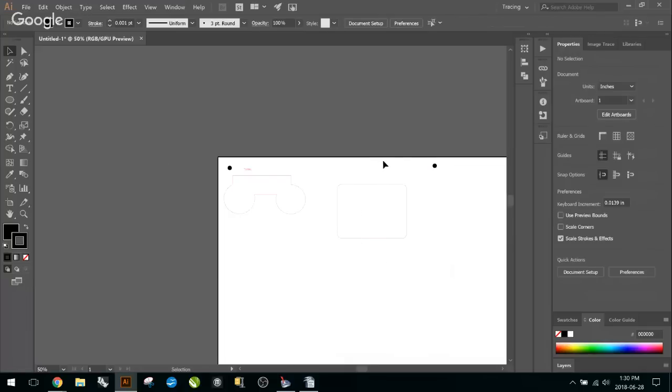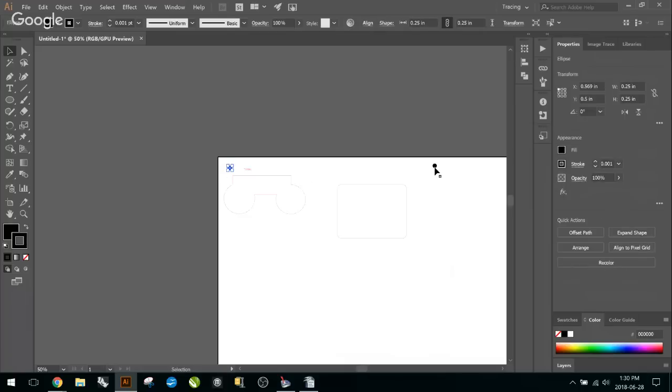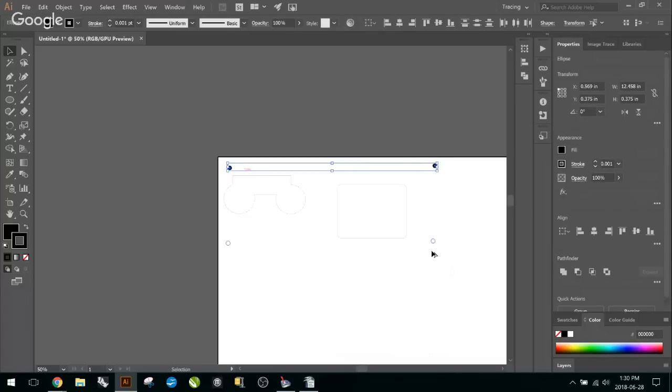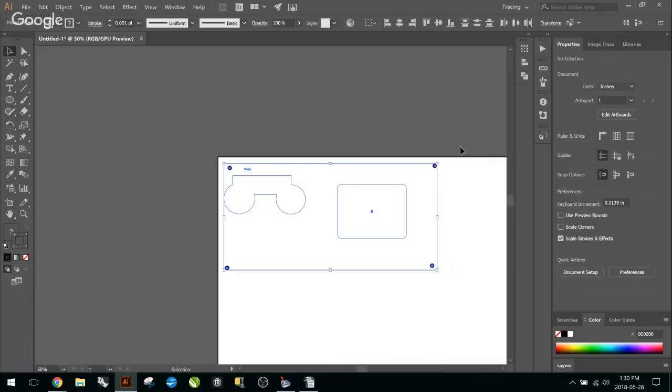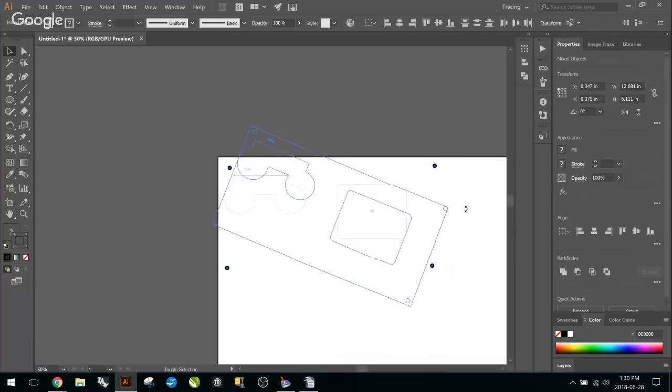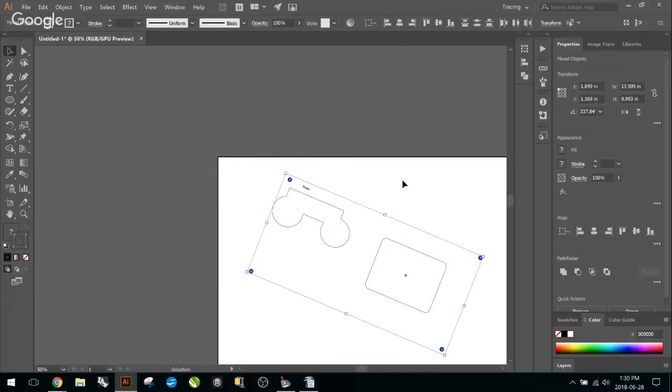So for instance, if our material here that is 12 by 24 was an odd shape, maybe it wasn't a perfect square, you can lay some registration marks here. Now once you put your odd shape material into the laser, the camera will find those registration marks and cut on those cut lines, no matter what orientation your cut lines may be in. So even if they're moving around an organic shape, you should still be able to cut exactly where you need to cut.